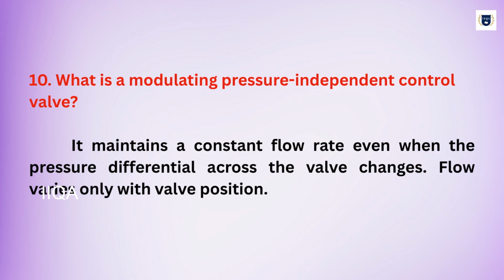What is a modulating pressure-independent control valve? It maintains a constant flow rate even when the pressure differential across the valve changes. Flow varies only with valve position.